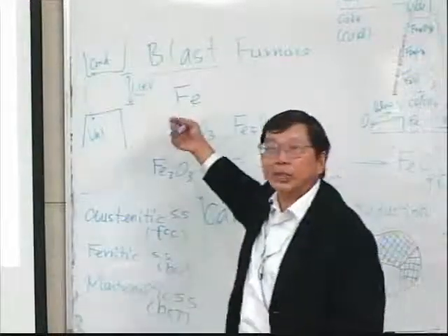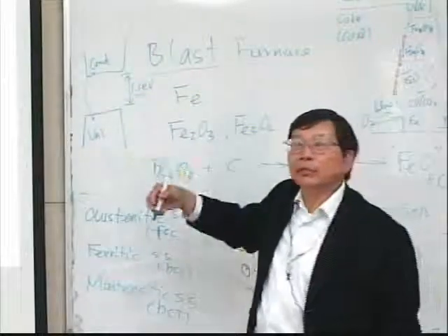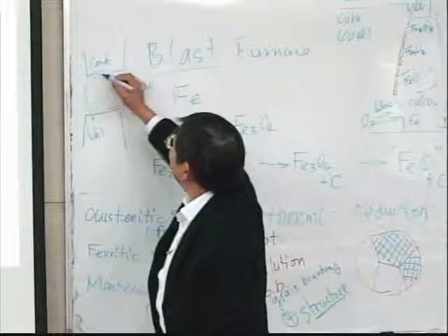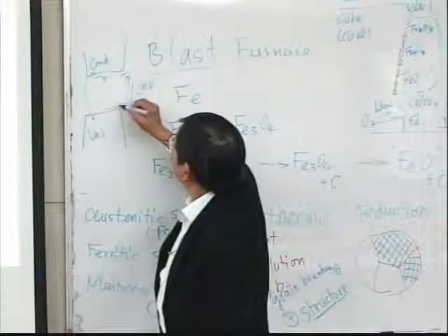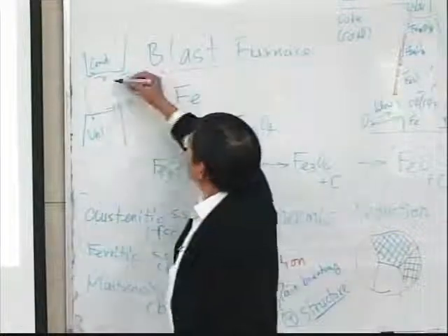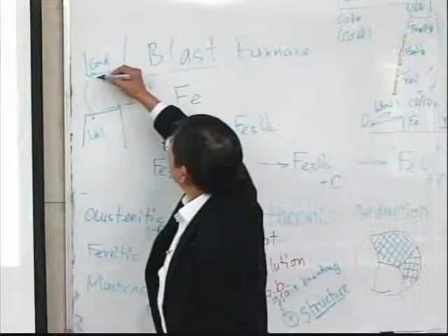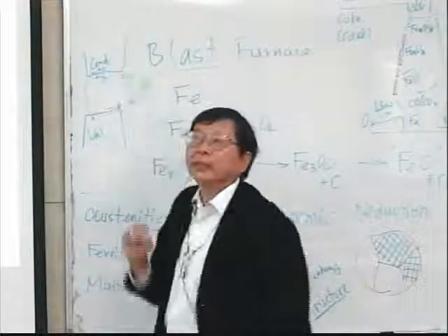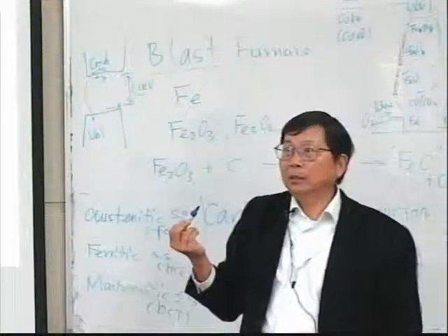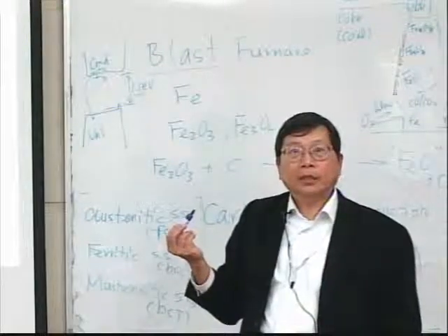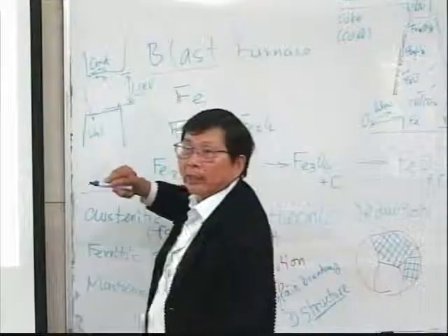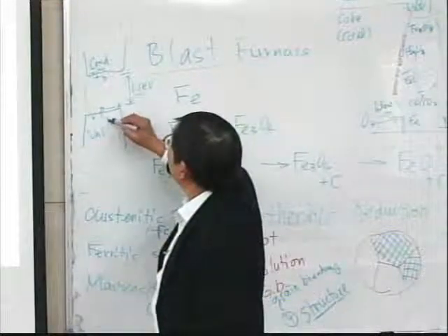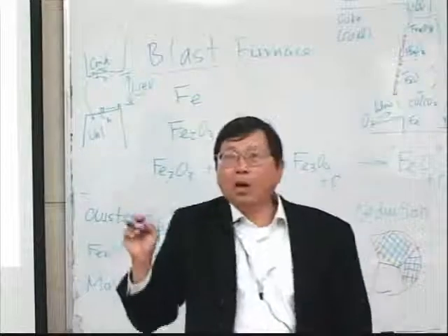Now, this is by nature. It's called intrinsic. If you put in an acceptor here or a donor there, then you can allow the donor to donate an electron in here and easily make it a conductor by doping. Or if you put an acceptor in here, you can easily allow an electron to jump in here, and you create an electron hole down there.